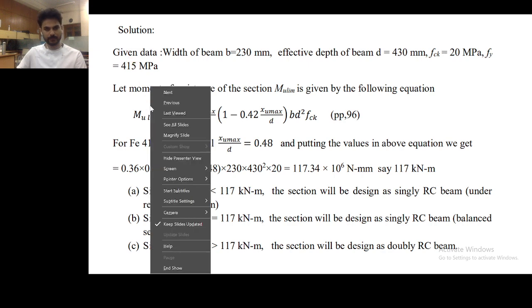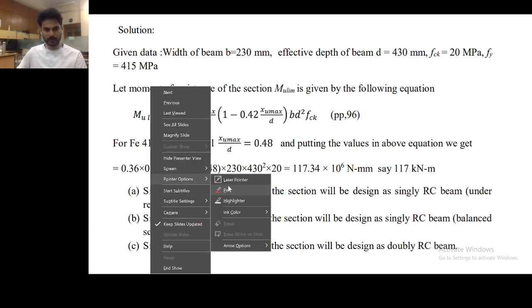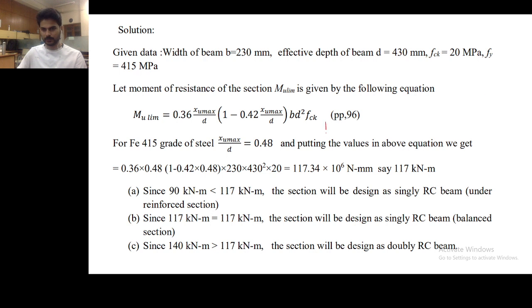Okay, we will discuss this and then we will move forward. So this is the beam. In practice we always provide the steel at the bottom and at the top also. Why is that so? Even if the compression steel is not required, still we provide it like that. So the answer for this is, anyone want to try? The answer is to hold the stirrups.